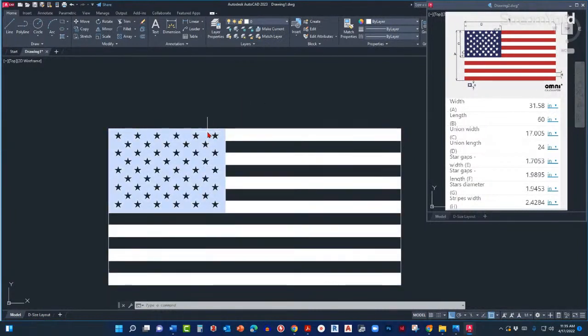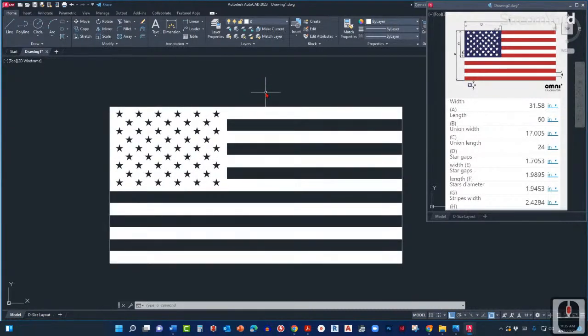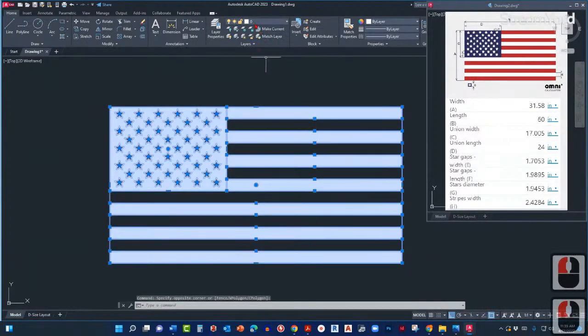So right now, all of the objects that we drew are on layer 0. You can see it here on the ribbon. It says layers provides a choice of layers to the current drawing. A good practice, especially when you are a beginner, is to not worry about layers at the beginning of drawing something. Simply draw everything on layer 0, and then you can start assigning layers in the end. Because especially if you're a beginner, if you try to worry about layers and objects at the same time, you will get confused. So again, that's why we draw everything on layer 0.